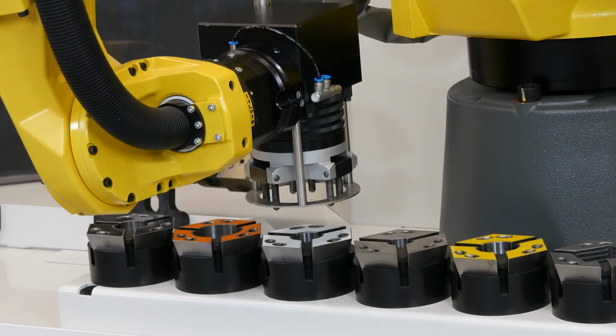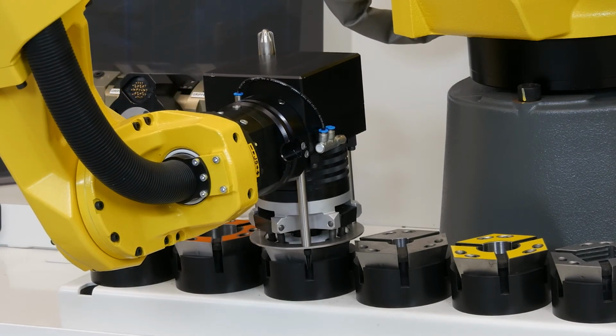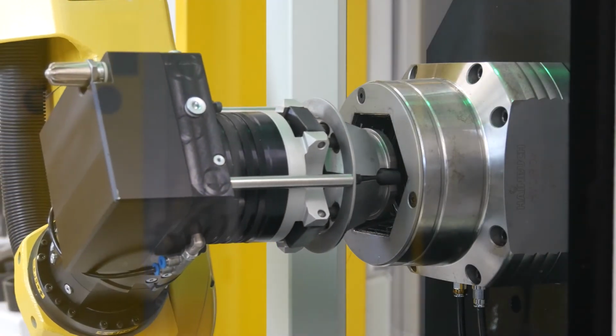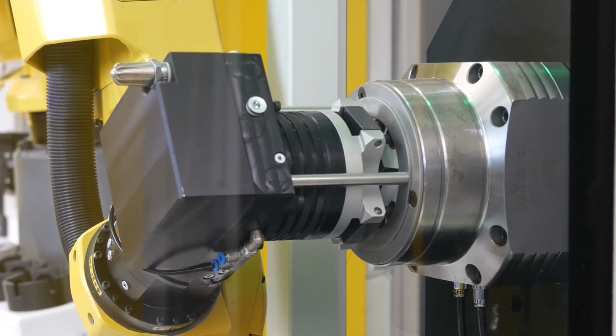We'd like to share the technology we use and also developments we see in the industry to use your machine more effectively. One of these functionalities is collet exchange, automatically exchange collets in your lathe. The robot will pick a collet, place this in your machine clamp, then go to pick a product from the tray and place this inside of the collet. Collets are often used for precise gripping, but also to automate various smaller jobs. Different small series can continue one after another without the need of manual changeover.